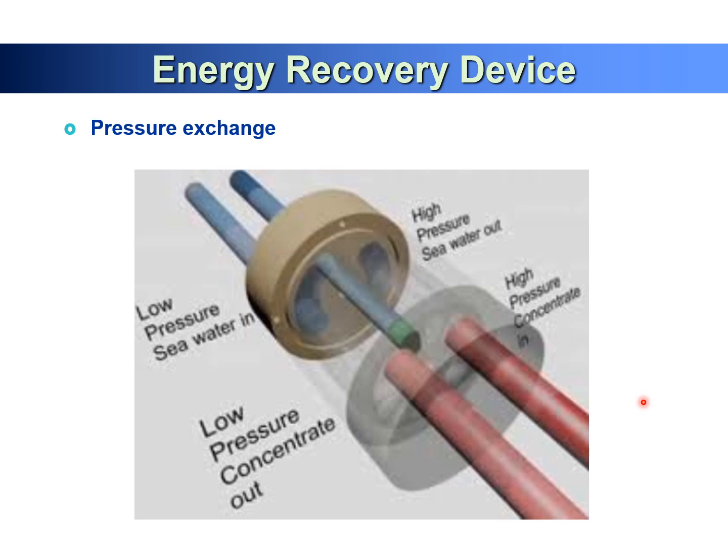So already, as this video shows, the pressure exchanger is one of the breakthroughs to reduce the cost of seawater desalination plants. So what happens is that this is the seawater, this is the ceramic rotation material, and seawater is flowing this way, and on the other side we have a high pressure concentrate, almost 60 bar, and because of this pressure, this will rotate this ceramic material,